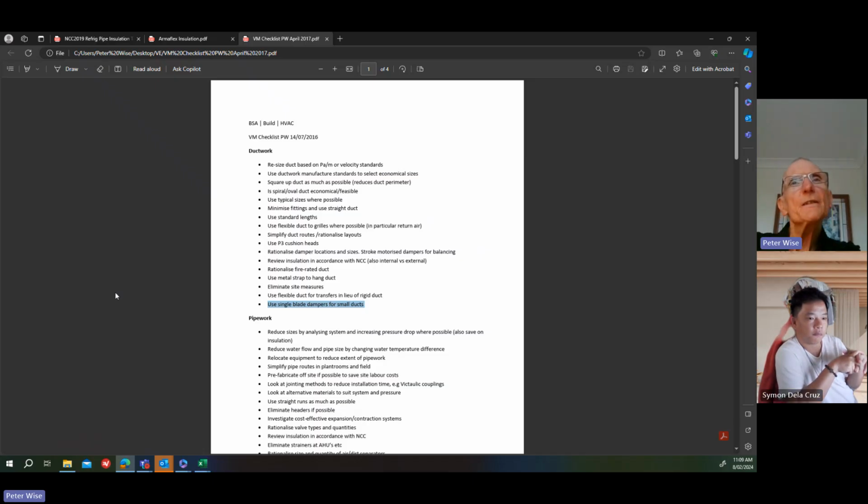But we used to say probably up to 400 wide by 300 high or something like that. Above that, they're too big and they vibrate and they don't control very well. But for small ducts, they work all right. So 400 by 300 would be okay, probably up to that size.